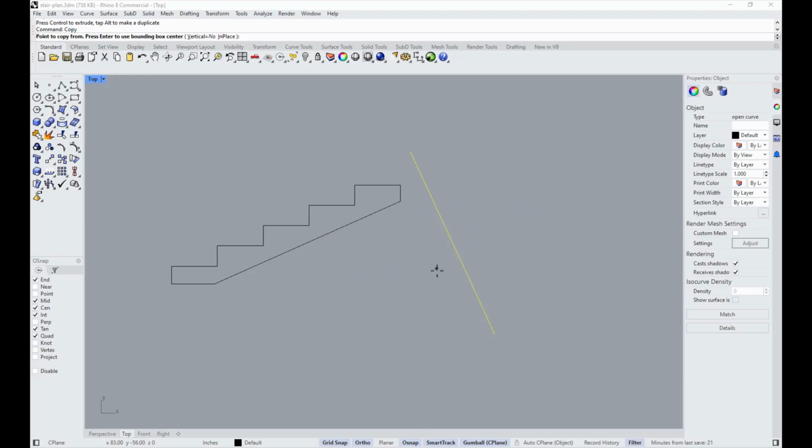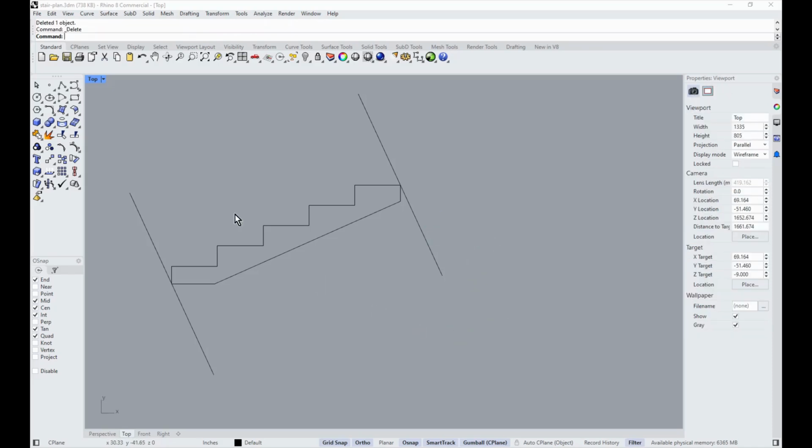Let's see here. I'm going to copy this thing over. And again, the commands I'm using are kind of universal for anything that has one-to-one sketching. Rhino's really good with it. But AutoCAD can do something very similar. So this is a critical dimension I did here. I took this bottom part of the stringer, I rotated it 90 degrees, and I copied it to these 2 points.